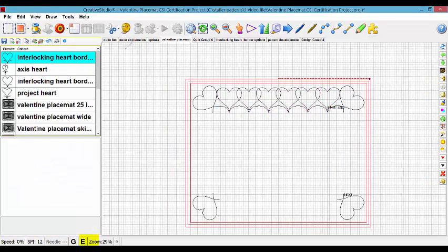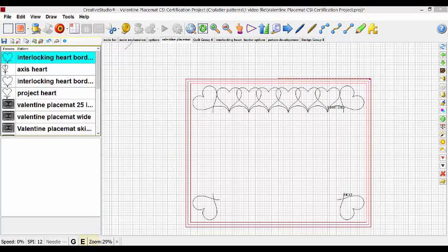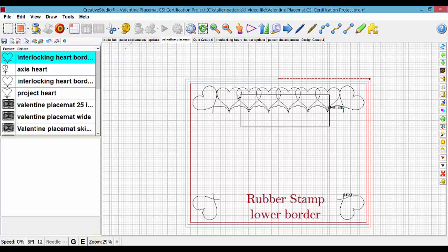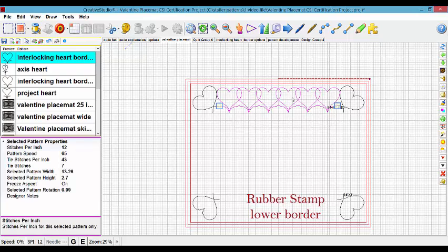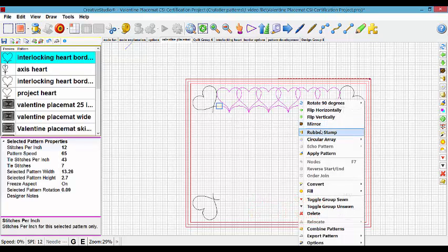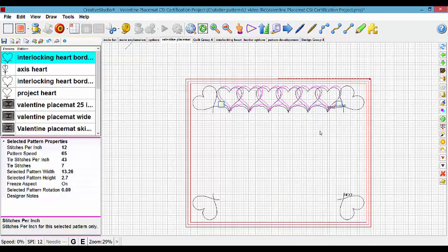We could repeat this process for the bottom border. Instead, we will rubber stamp the border pieces and then use the endpoint anchors to place our border. Select your border, rubber stamp, press the Escape key on your keyboard. This activates the last placed pattern as your active selection. Now using the endpoint anchors, snap the rubber stamped border in place between the two bottom corner pieces.